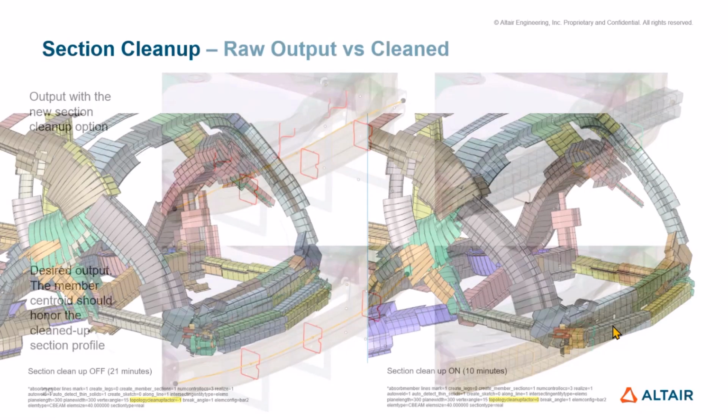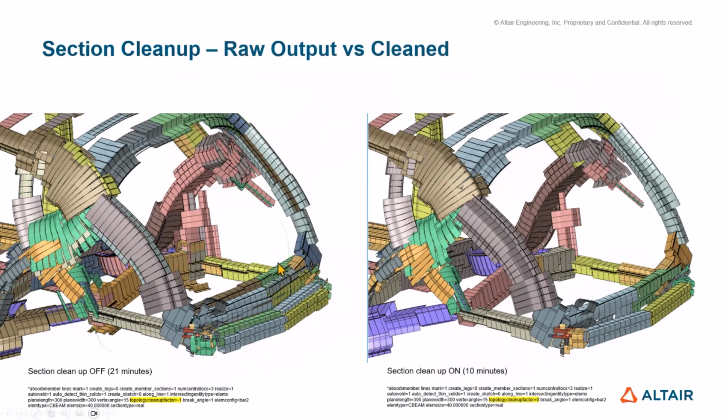Before I do that, I just wanted to show you this slide here. This was a full model with the raw output from the line extract. It wasn't cleaned up, so there's an awful lot of noise in this model already. This was really just a dumb academic performance test. You could see that without the section cleanup, it was taking around 21 minutes. With the section cleanup on, it's taking 10 minutes.